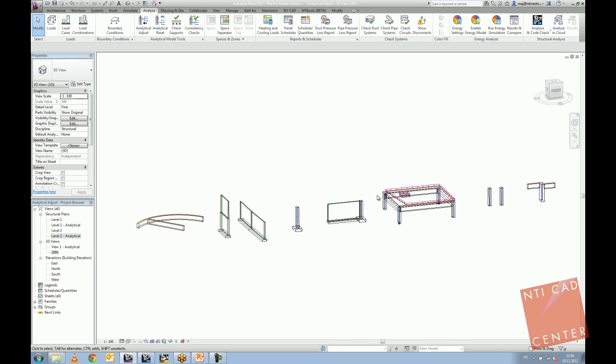If, at the very end, when the whole structure is modeled, you have a model where nobody looked at the analytical model, and you need to do the analysis the same day, expecting to have a Revit model and do the analysis the same day just because you have this analytical model and this wonderful integration, well, that might not just work, because then you need to put a lot of effort into closing all of these small gaps, etc. and fixing all of the analytical model. So it's always easier if the person who's modeling has a focus on the analytical model and does it correctly from the start. Then it's way easier to control the whole workflow.